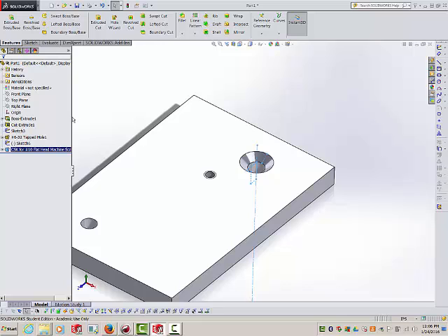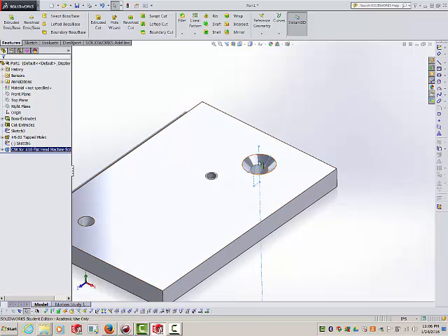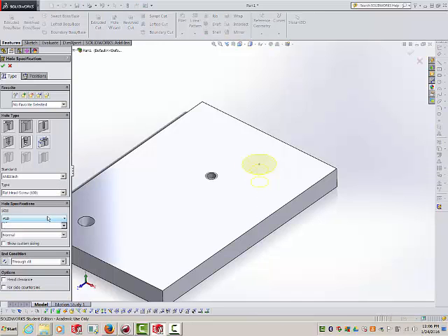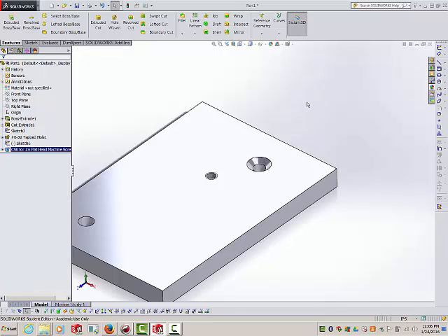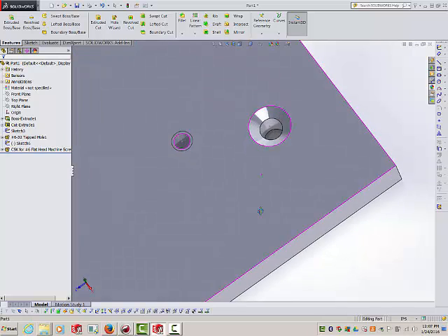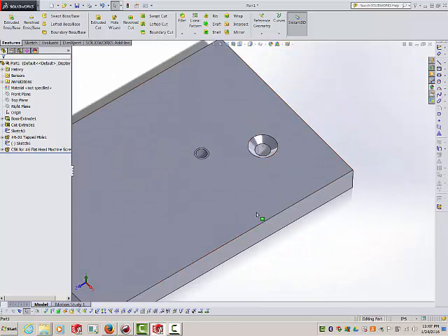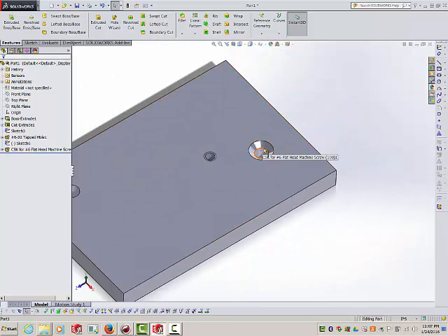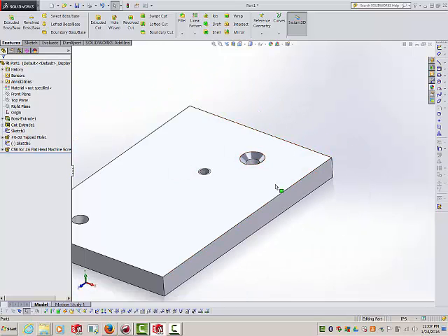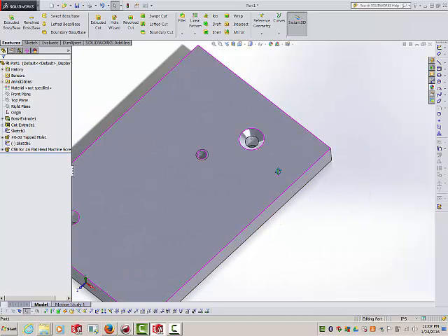countersink flathead machine screw. Now, if I didn't like that, and said, well, my design, I wanted to do something different, I want to do a smaller hole, significantly smaller, maybe back down to a 6. It's just a matter of changing that. And the neat thing is when we do our drawing, it'll allow me to grab the callouts for this entire flathead countersink and not have to worry about detailing it in when I do my drawing.